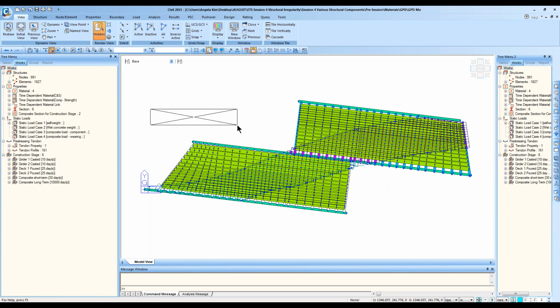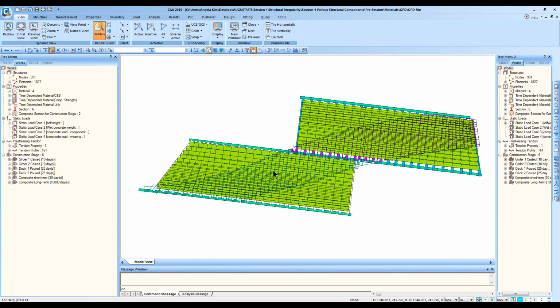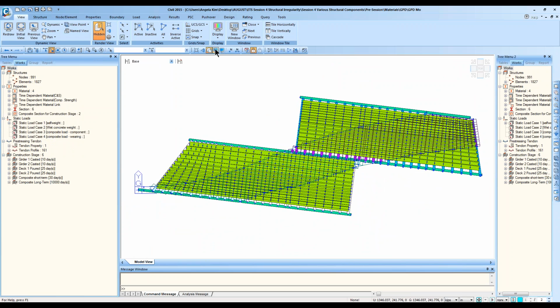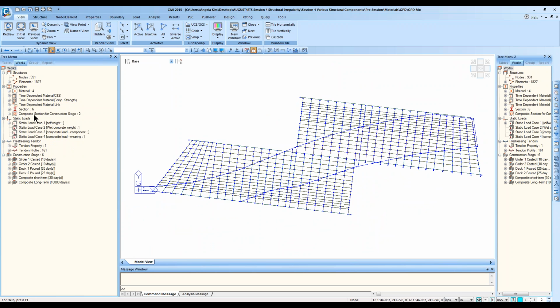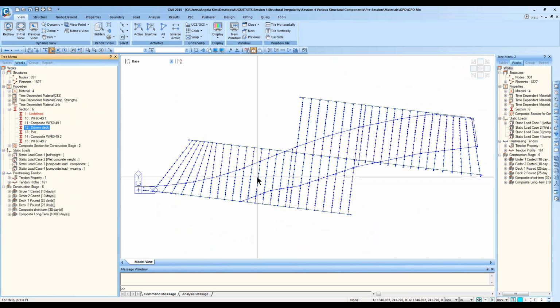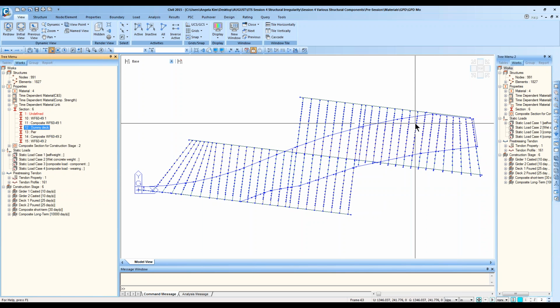And for this example too, remember that right now our girders are running in the vertical direction, I mean the transverse direction. And the deck isn't geometrically perpendicular or parallel to the girder; it's neither of the cases. So in this case, what you will need to set up the moving load analysis is to use this deck outline line, or you could draw a dummy beam that could be the reference line for the moving load analysis.